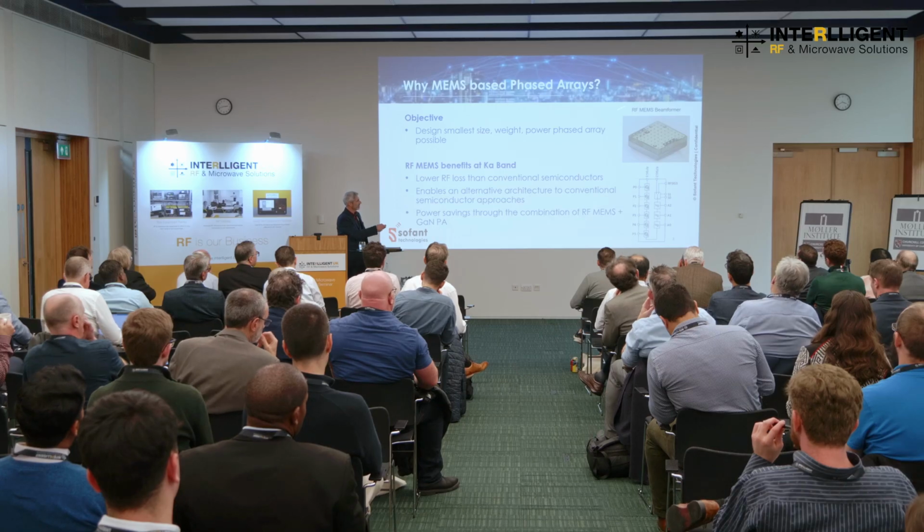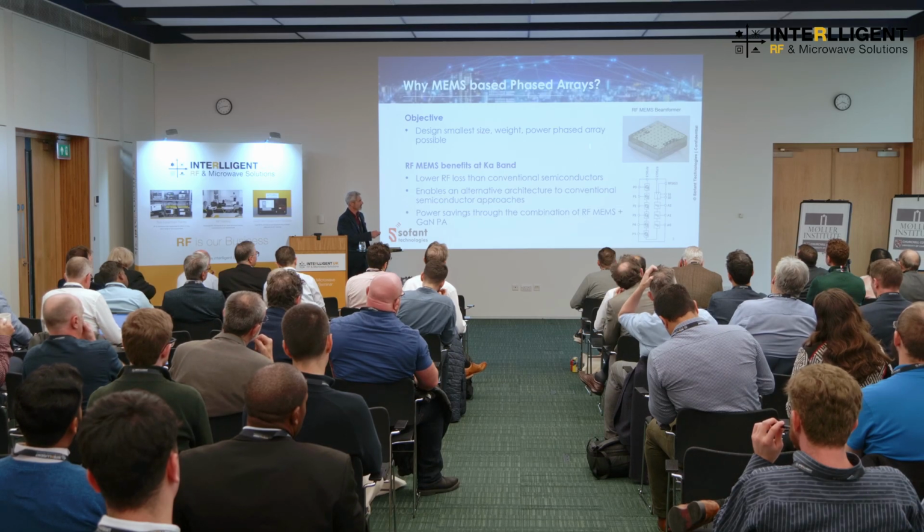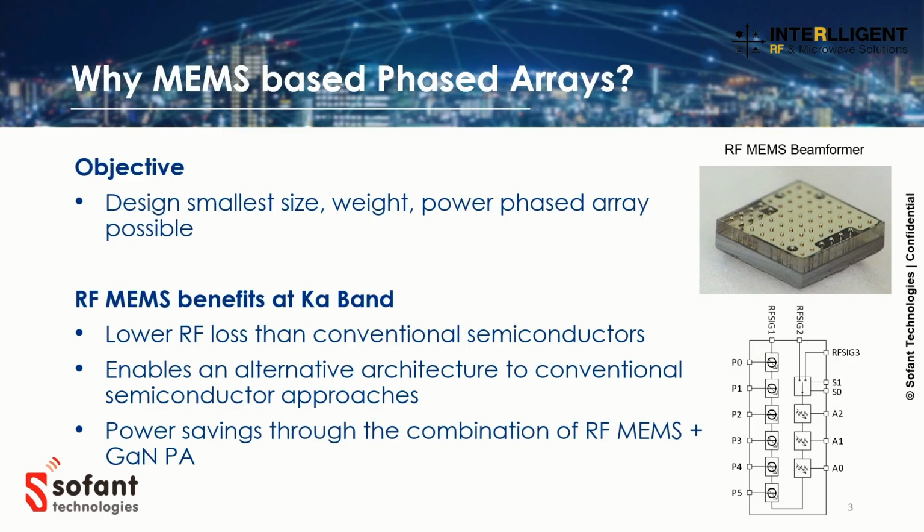This is just an image showing one of our RF MEMS devices. You can see there's a number of IOs. I won't go into all the detail, but here's a very simplified block diagram. It's quite a conventional solution in terms of functionality: 6 bits of phase shift, 3 bits of attenuation,